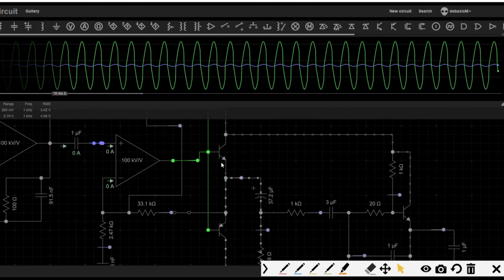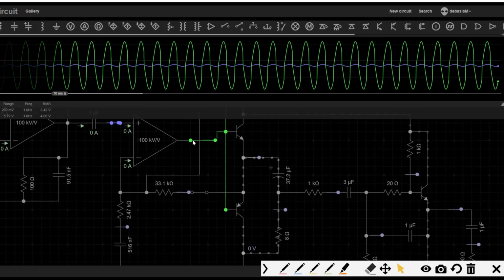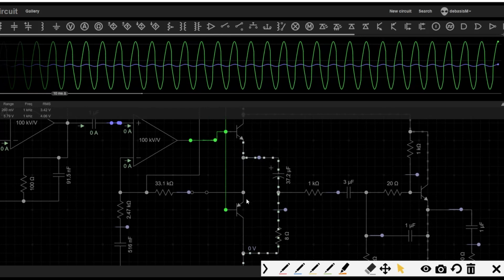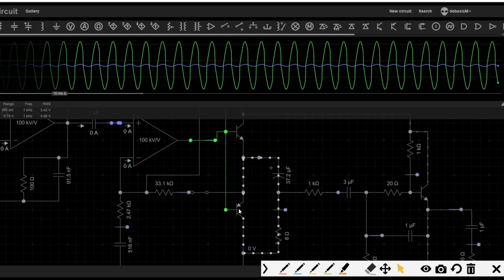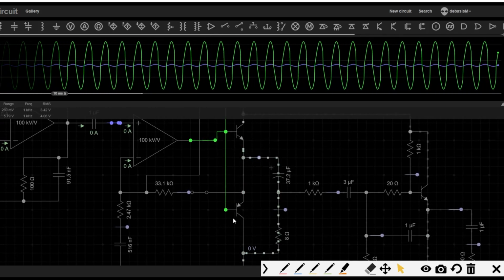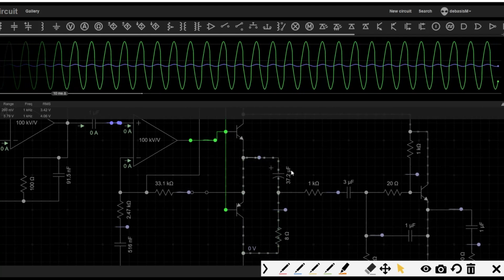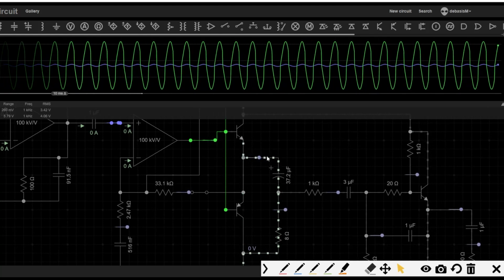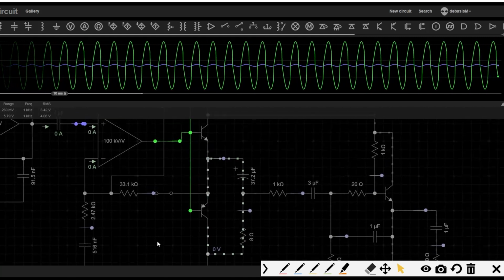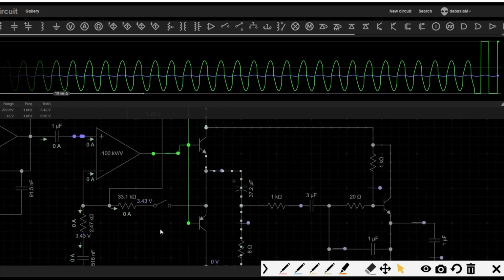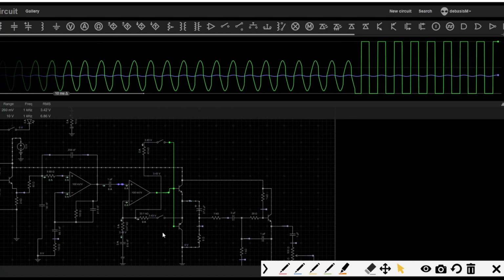So this is going to close, and at that time, when this goes low, this PNP transistor is going to go active. So in the negative cycle this is active, and in the positive cycle the other is active. Alternatively they take charge and allow the flow of current through the circuit, the way the animation is showing. Now there is a catch. See here what is happening.